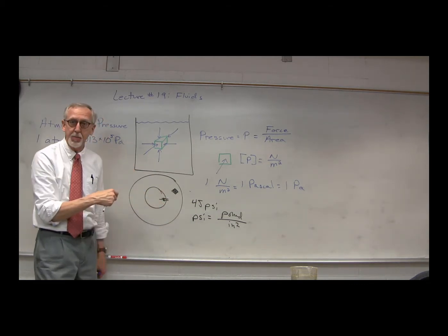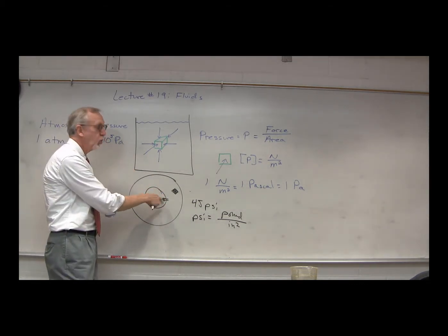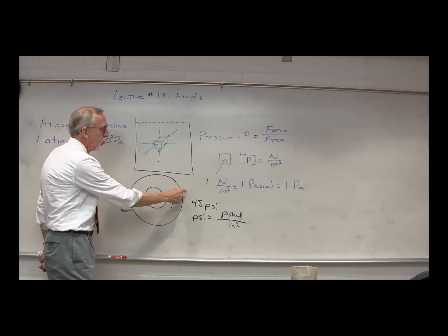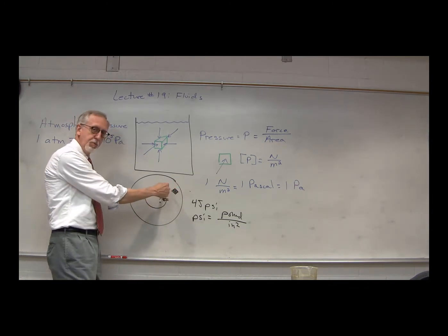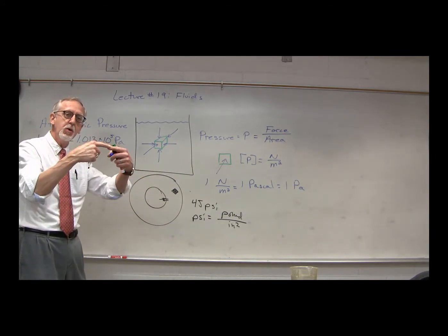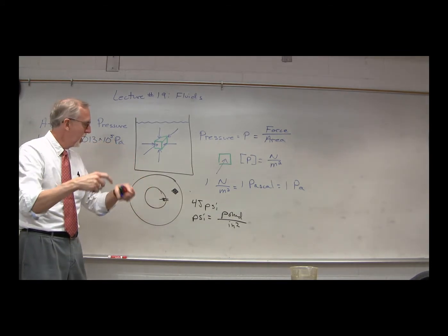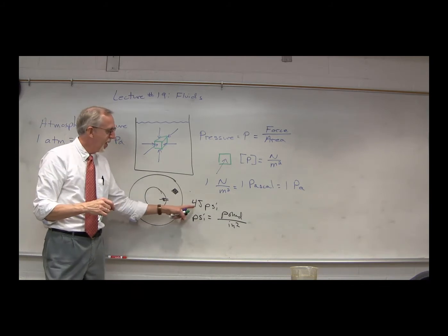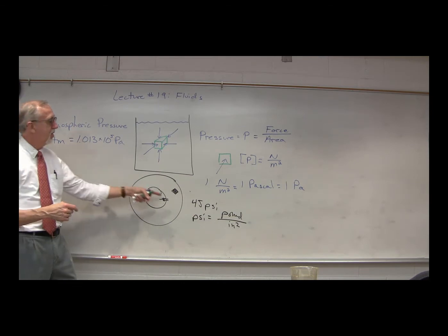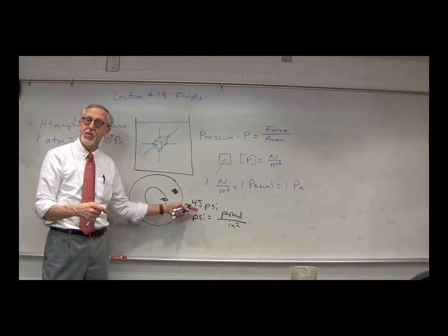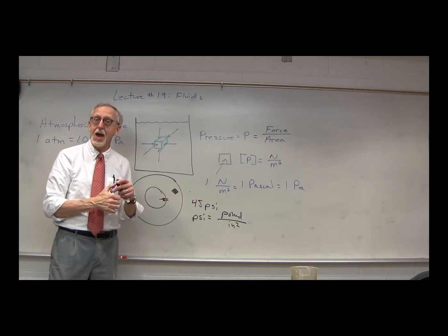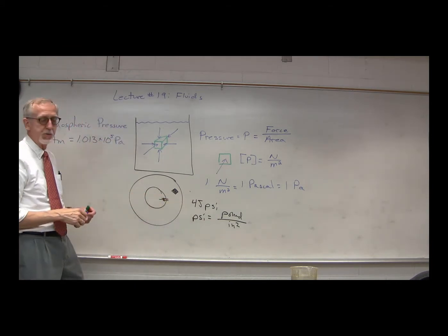Imagine you take the entire hubcap out, not the hubcap, but the wheel rim. Take that completely out, so you just have the rubber tire. Well, you'd have 1 atmosphere of pressure on the inside pushing in on the tire, but 1 atmosphere on the outside pushing out. You'd have equal pressures pushing in and out. This 45 psi, that pressure is actually above the atmospheric pressure. So that extra pressure is what the 45 psi means. It's actually above and beyond, so to speak, the atmospheric pressure. Okay, so that's what that means. Very, very good.